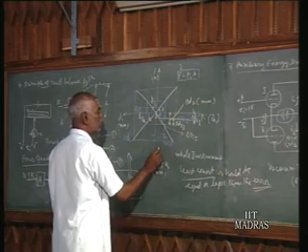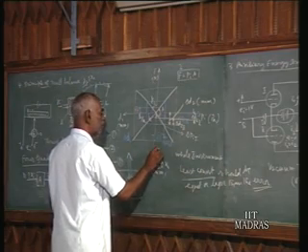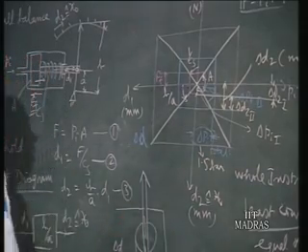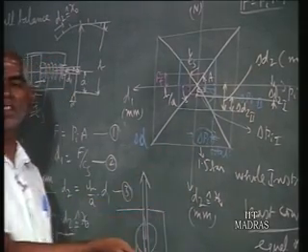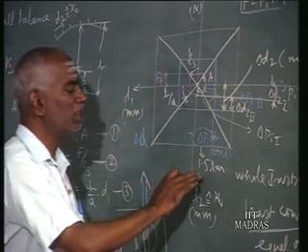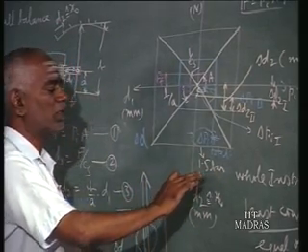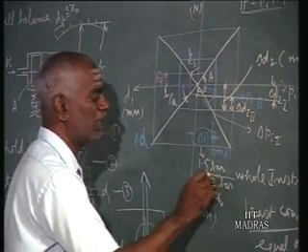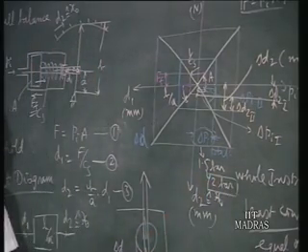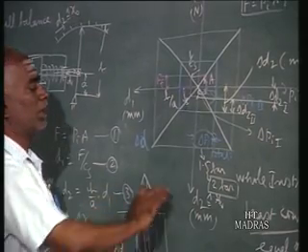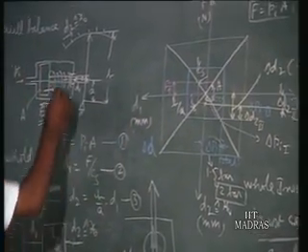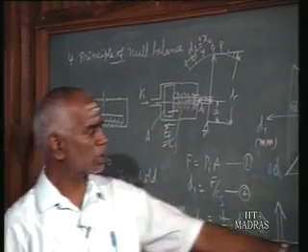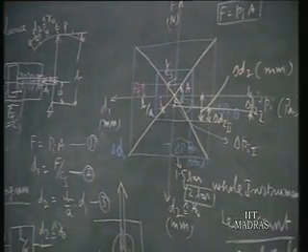Suppose delta pi is equal to 1.5 bar, then the least count should be equal to 1.5 or it can be larger, but normally the least count is in terms of full numbers. So the next higher number will be 2 bar. Select the least count as 2 bar. So for this instrument you will have least count graduations of 0, 2, 4, 6 and 8 and so on. In fixing the least count we have made use of the 4-quadrant diagram.